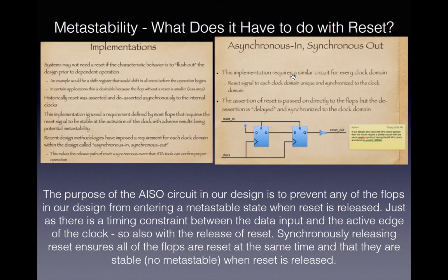Some systems, I agree, don't require a reset. As we've mentioned in ASIC design, a flop with a reset is more expensive, so it may be prudent to not include a reset. That would be perhaps a camera processing video data. Once the video data starts streaming, it just initializes all the flops to a known value.